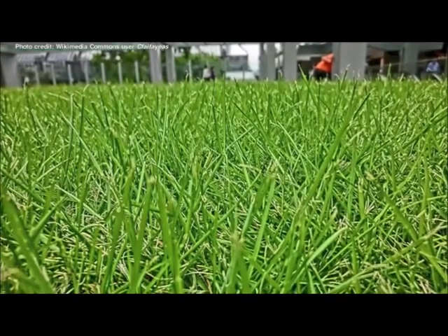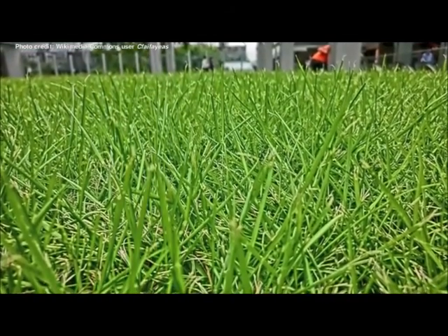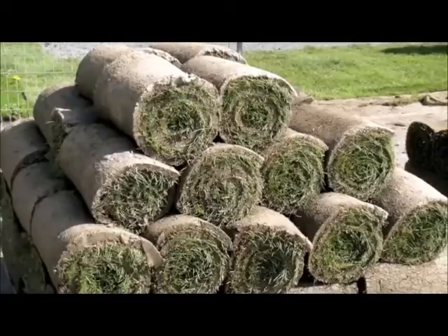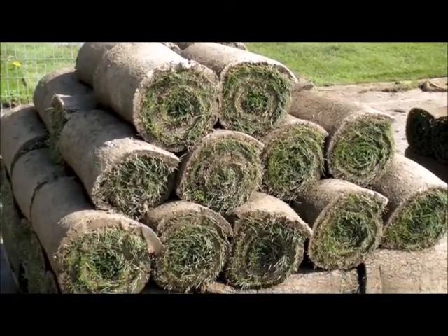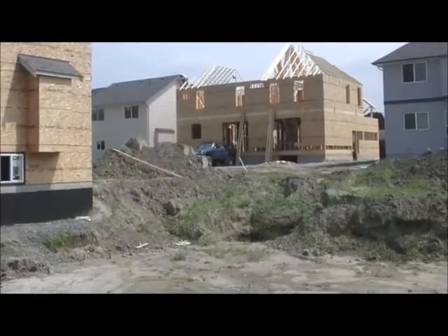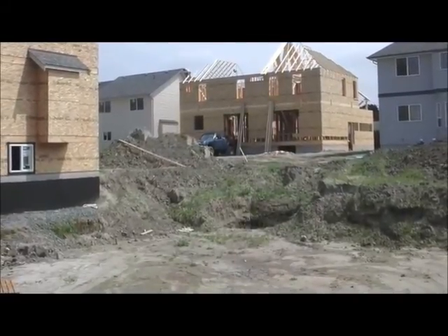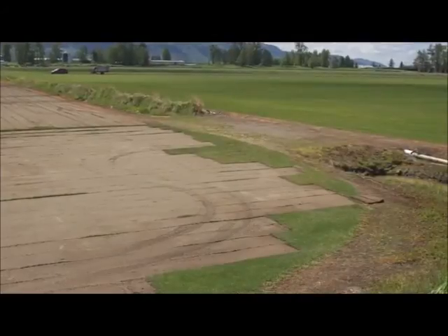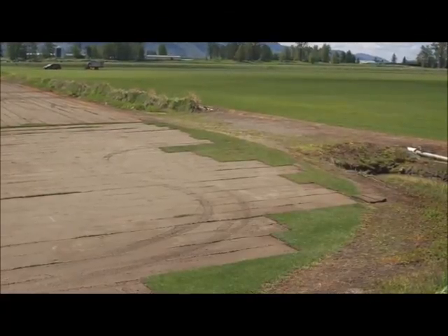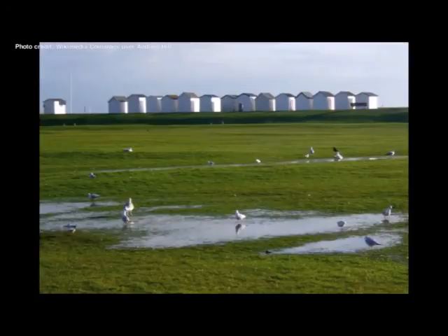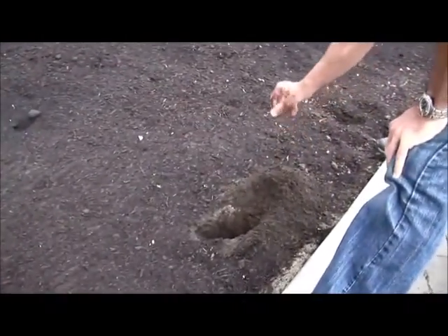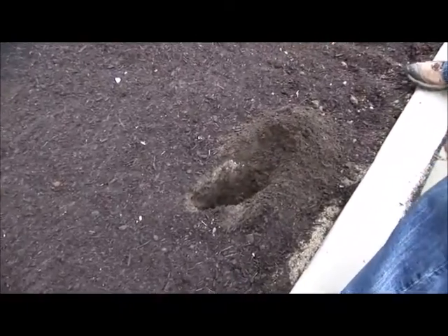It may seem that a grass lawn is a good option to allow infiltration on a property, but that's not true when turf is rolled over compacted soil. This is common when construction uses heavy machinery. The soil is so hard, it is as though grass has been laid over concrete. Unsurprisingly, this leads to drainage problems, pooling, and runoff during heavy rains. Adding a layer of topsoil can alleviate this problem.